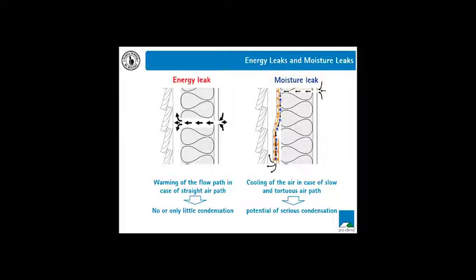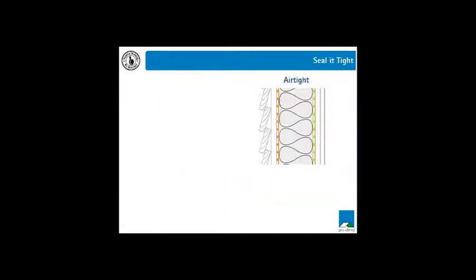The solution to both these problems is simply build it tight. Build it very tight, as tight as you can build it. That stops the moisture from going into the construction system to places where you don't want it to go. And this is how you build healthy buildings.